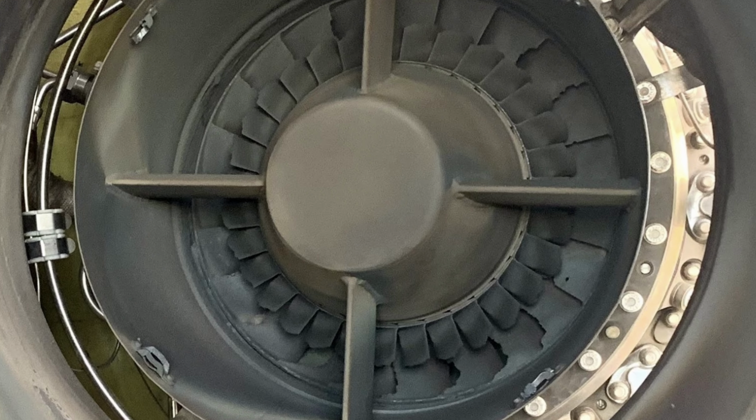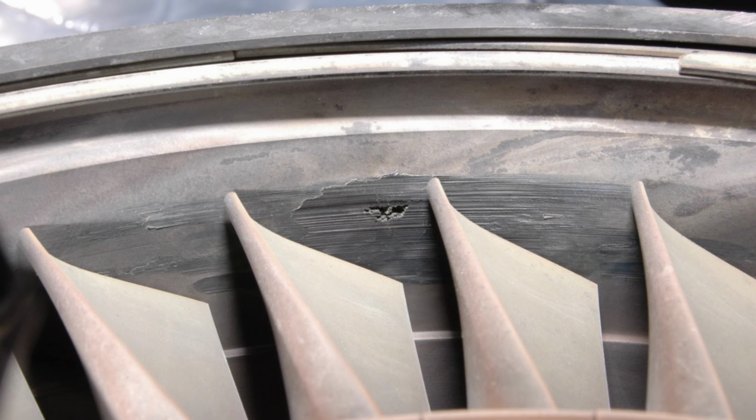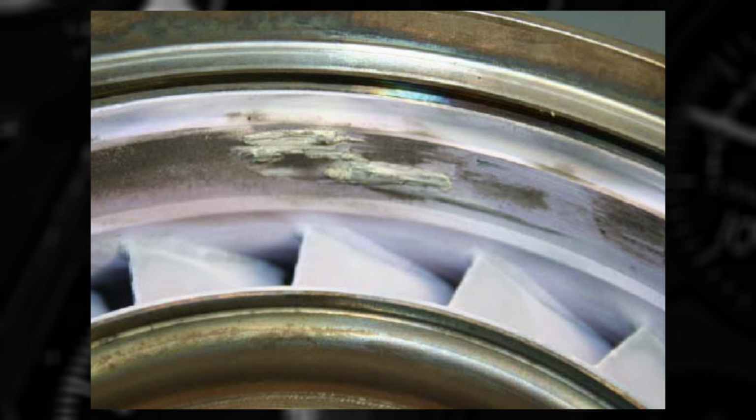Damage to the power turbine, such as impacts and distortion, erosion, corrosion, and cracks on the stators, affects the efficiency of these expansion stages. The most significant issue in this area is rubbing, which causes a reduction on the turbine's expansion ratio and efficiency, which significantly lowers engine performance, generally by affecting the power without reducing the temperature margin.